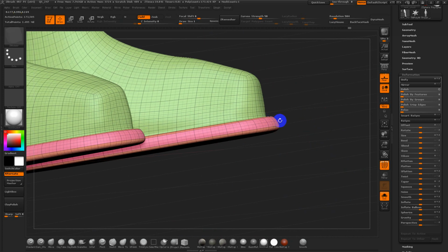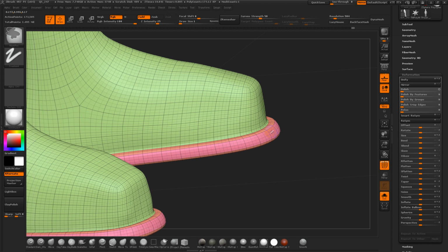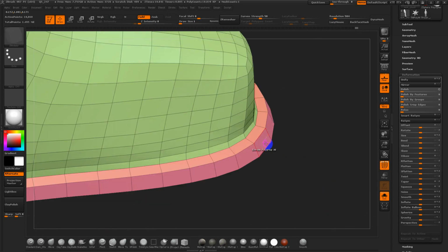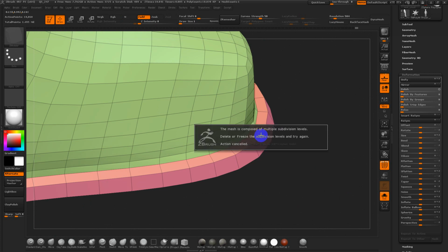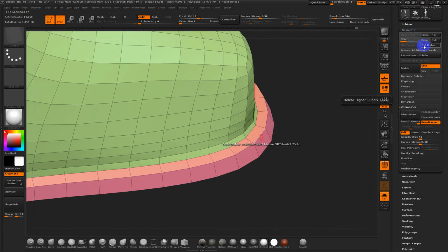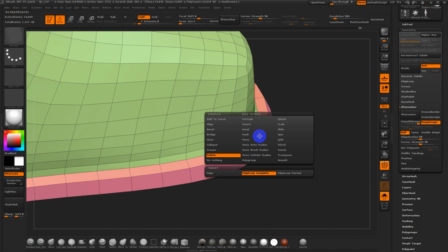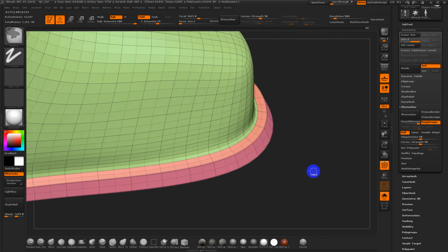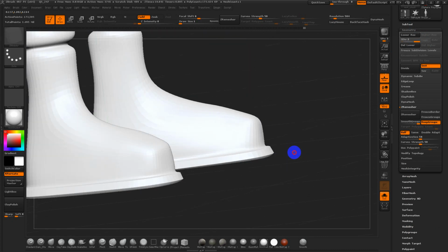So if I want to really make, let's say, this side, so I've divided, by the way, a couple times just to illustrate this. Also, if you go to edge mode, let me just make sure I have no divisions. So I'll delete the higher ones that I just added. But instead of going to delete, I go to crease, edge loop complete. If I crease this and crease this, now when I hit Control D to divide, it gives me a super sharp loop.